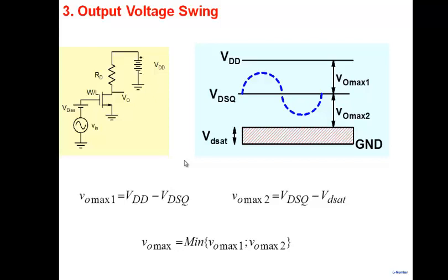But remember, these are the hard limits. As I said, even before it touches this, goes into this forbidden region, there is a harmonic distortion. And for your application, even before it touches this, the harmonic distortion may be too large. It may be unacceptable. So what I'm talking about is, these are the absolute limits on V0. For hardly any application would you go beyond these limits. Okay? Alright, so this is the kind of diagram that you need to draw in general